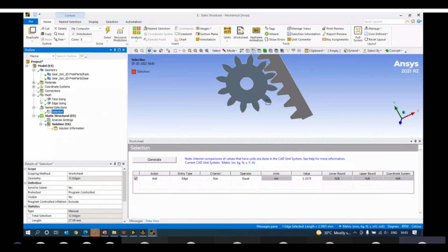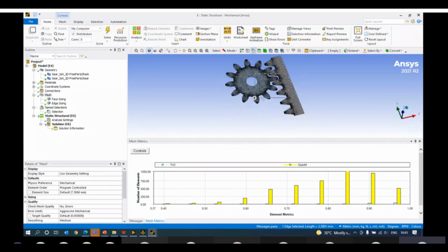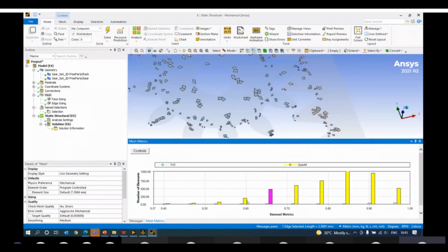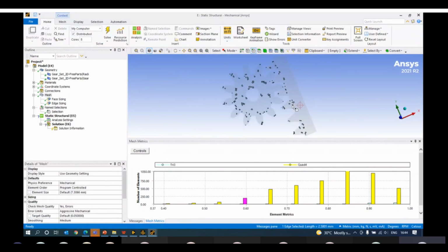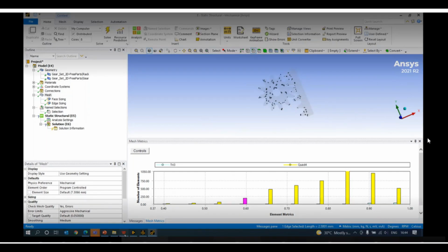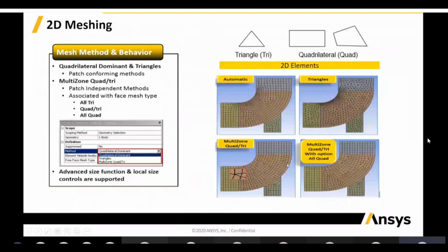this kind of issues. And as of now, when you look at your geometry here, 0.7 to 1, if your maximum elements are coming up, that is quite acceptable. But in case you want to proceed further to have good quality of elements, then definitely you have to struggle a lot, and you have to work with the different local controls and all whatever exist. Okay, so most of our issue with the edges is resolved. A few more techniques we'll see further when we are proceeding. So let's understand what else can be done.